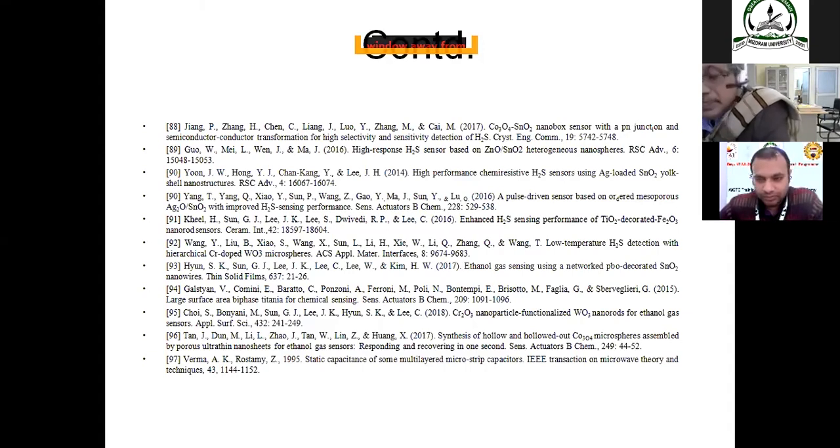We may have to use it at the seashore, especially for food, fish, and meat quality detection. A flexible sensor may have to be used at the seashore or in places where the environment is very bad. So it is difficult. We have to test all these things, and check humidity and everything. If you know the noise, the known noise, we calibrate for it, for example pH value. Under those conditions we have to calibrate the sensor. Then only can we avoid this problem.